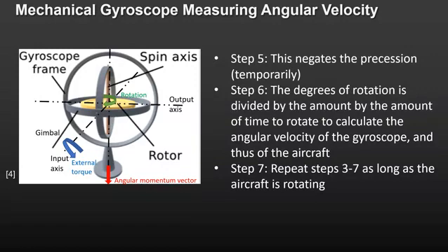Each of steps 3 to 7 in this recipe is repeated as long as the aircraft is still rotating. If the number of calculations is large enough, you can also take the differential of the velocity over time in software and calculate an angular acceleration.